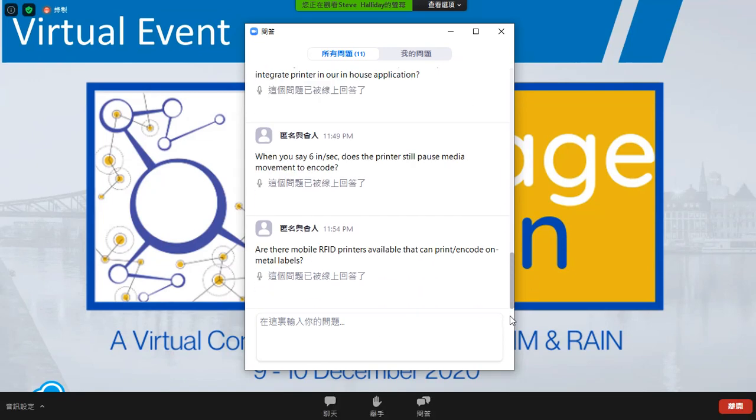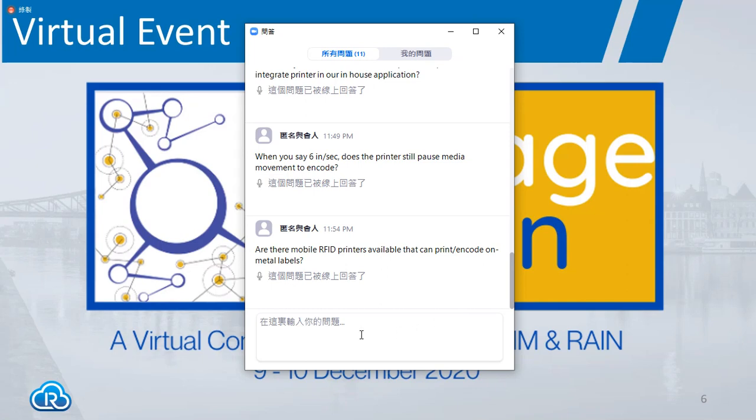Very good question. That gets more into the application side of things, which I am not an expert on, but the answer would generally be you cannot. Yeah, I think there are ways to assist you in doing that, but it depends a lot on the metal that's surrounding the tag. We all know that metal is not truly radio frequency friendly. And if there is sufficient metal in the way of the tag, you won't be able to read it. But radio waves also bounce off of metal, and sometimes it's possible to see a chip that you would have thought you would not be able to read.